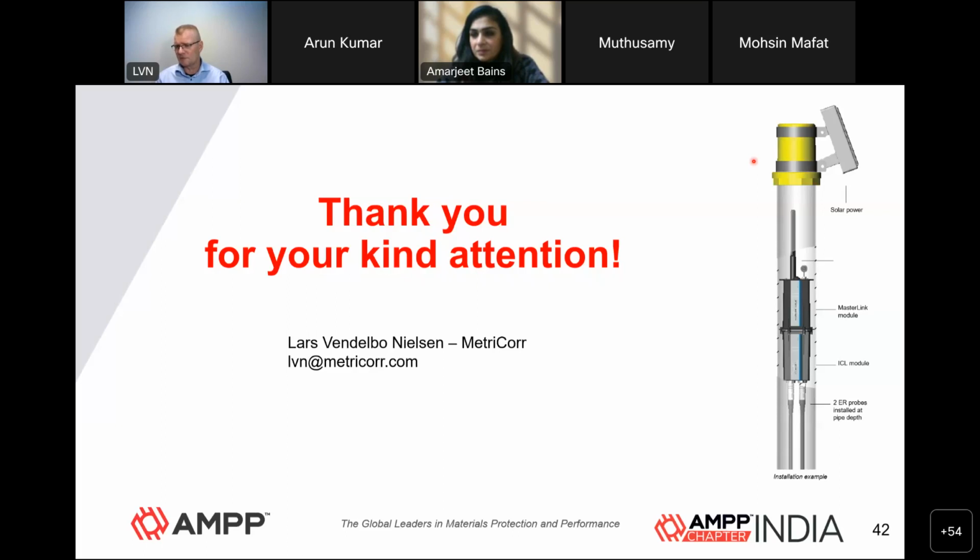So the use of solar panels is a very common, or at least a robust, way to provide power to the electronics that you embed in the test post. If you have problems with vandalism, of course, this type of test station, where you signal that you have some instrumentation inside, may not be the best. But that's where we have the underground bullet, so that you can hide completely what you have. And of course, that has to be combined with a battery.